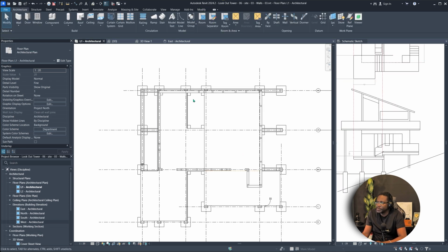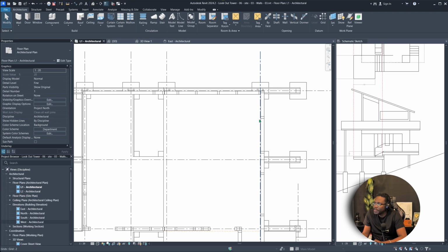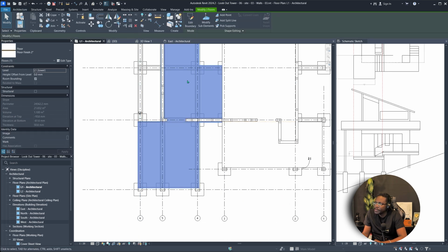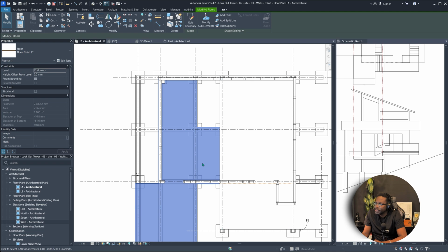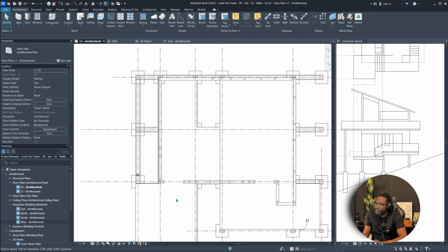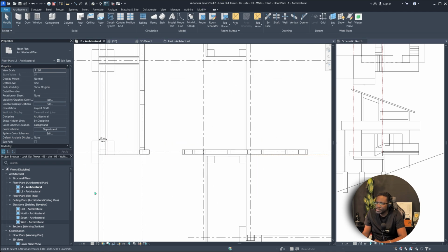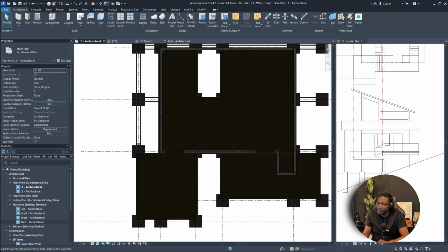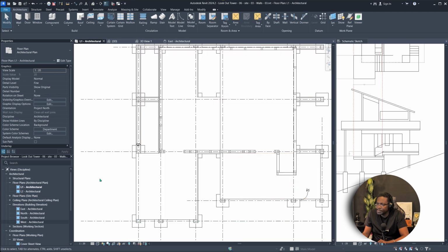So it's going to delete the drawing as well. Now in this plan view, notice that the floor is not showing the wood material, but that's okay. We can still identify where it is, or we could go to shaded view. That would show us where it is there. So I'm going to keep it on hidden line.